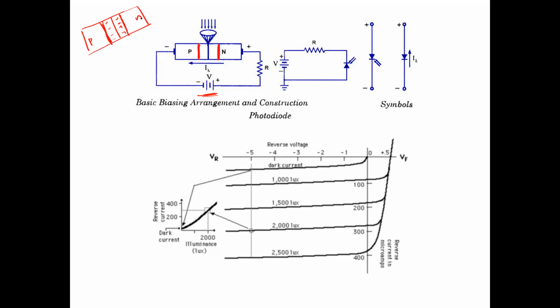In n-type material, electrons are the majority carriers and holes are the minority carriers. The depletion region is formed when some of the electrons jump from the n side to the p side and some of the holes jump from the p side to the n side. So a charge neutral region is created at the junction, and if it is forward biased, the depletion region is supposed to shrink. If it is reverse biased, the depletion region is supposed to increase.